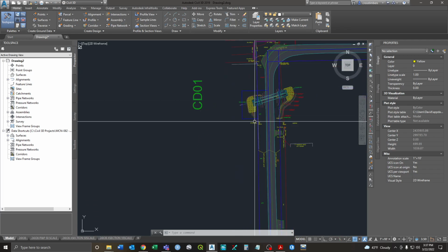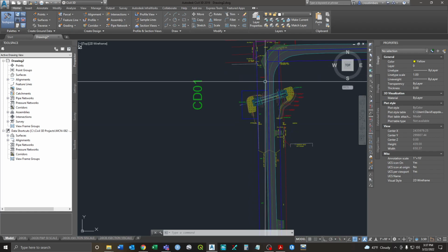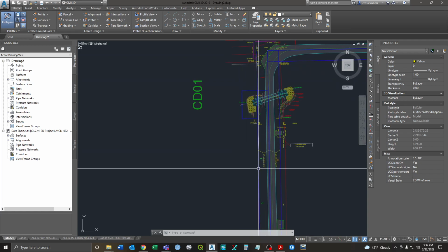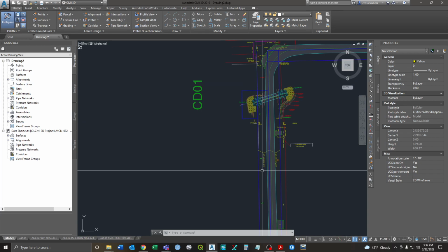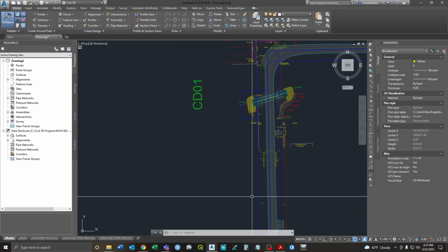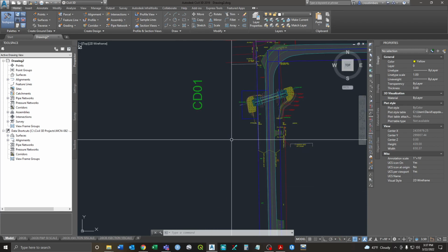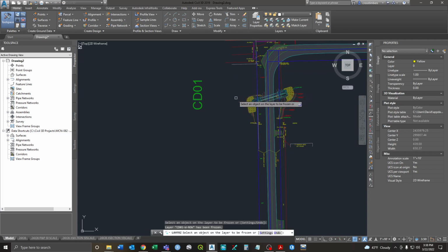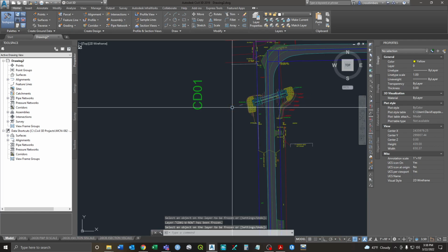And down the road, this is just an overlay, so we really don't go outside the boundaries of the roadway. But on full reconstruction stuff, you're going to have grading work and all kinds of stuff out here. So almost the whole way down, you're having to buy right of way. So all of these are connected to each other, but then there's tons of different properties, so you're going to have to constantly be breaking them up and stuff like that. So to me, it makes more sense if you put everything on its own layer, then you can kind of do everything one at a time and slowly work through that.